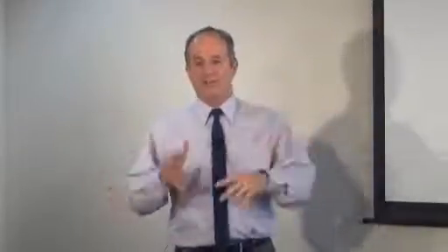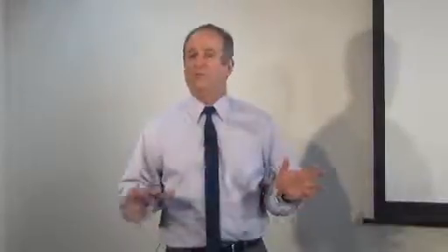That line's tripped. You're responsible for informing operations people who can go out to that substation, check it out, get another spare in there, and get everything back to normal as soon as you can. Meanwhile, you go back to your computer and figure out what the next worst contingency is. What do we have to do to minimize worst case scenarios? You don't want that cascading domino effect to occur. There could be problems with equipment or transmission lines.